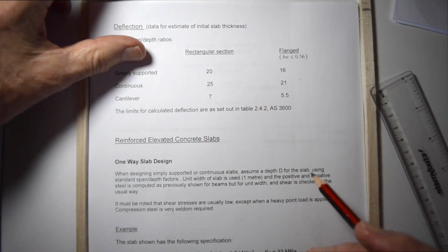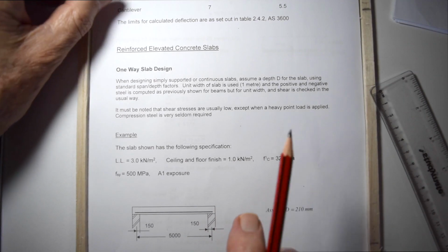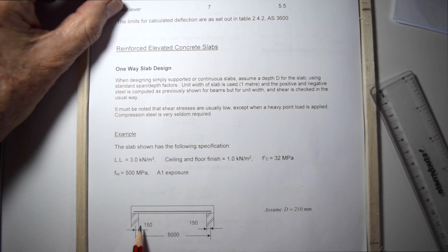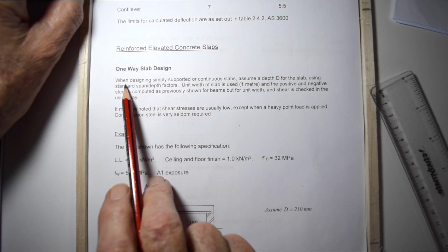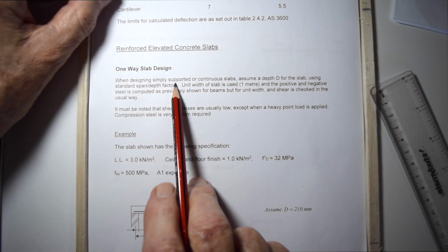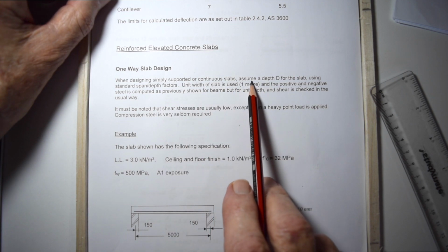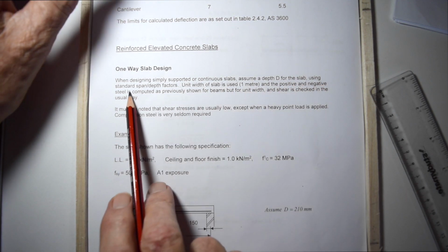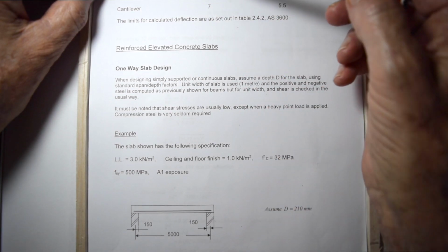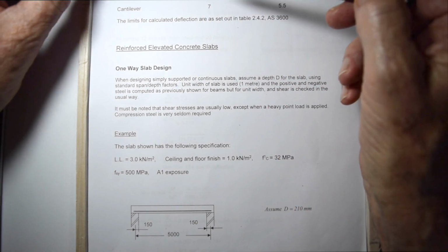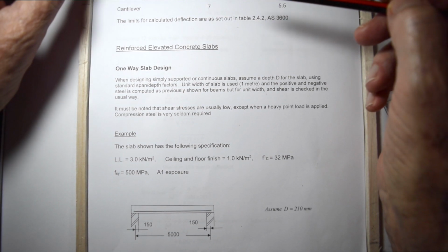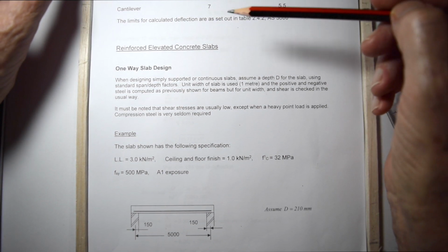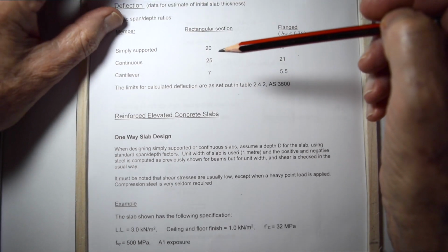So we're looking now at a one-way slab, this one there, spanning 5 meters, resting on brick walls. And when designing simply supported or continuous slabs, assume a depth for the slab using standard span depth ratios. And these are standard span depth ratios, and sometimes you do a bit of a thumb suck. You do the problem, it doesn't work out accurately, so by a process of iteration,